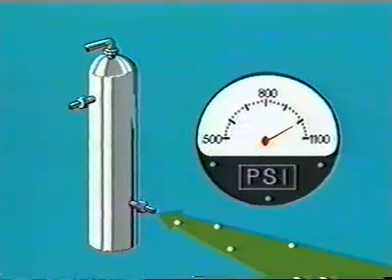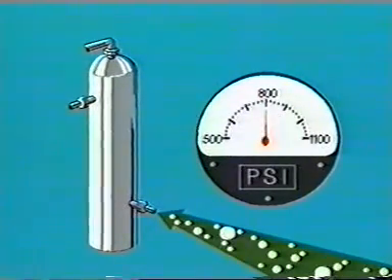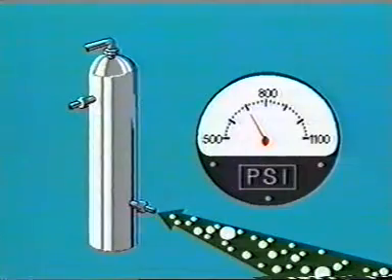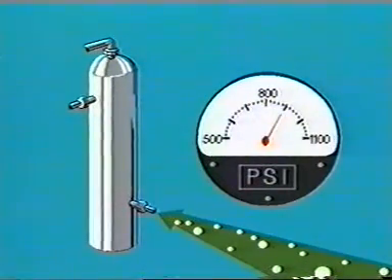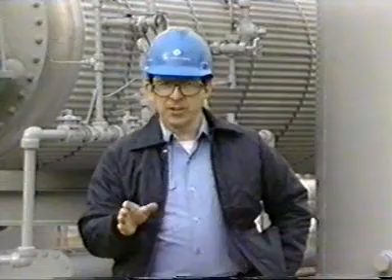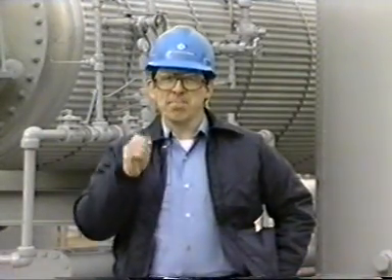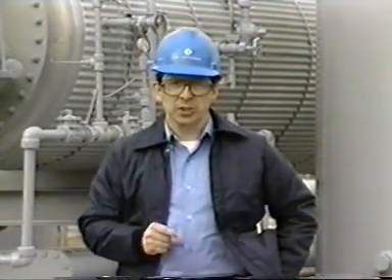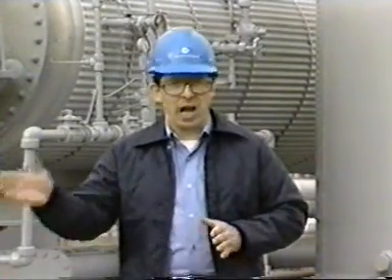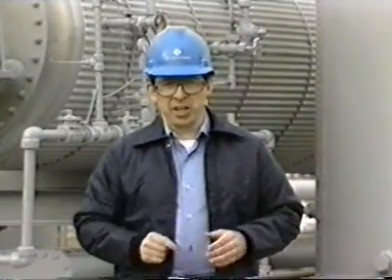However, at constant temperature, gas can hold more water as the pressure is reduced. Therefore, operating the unit with a higher inlet gas pressure will lower the water content of the gas. For a unit to operate efficiently, the gas flow rate must be maintained in a specific range. Now, if the flow rate falls outside these limits, either higher or lower, problems can develop.